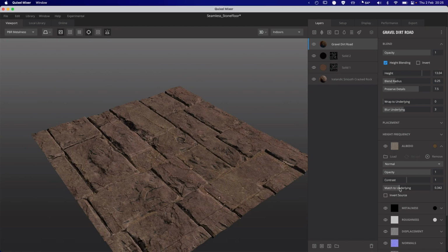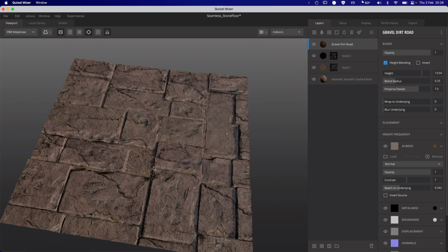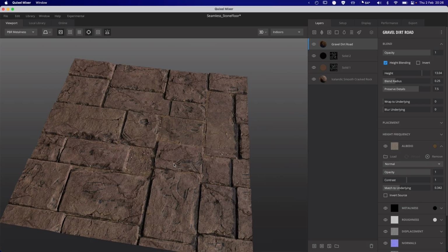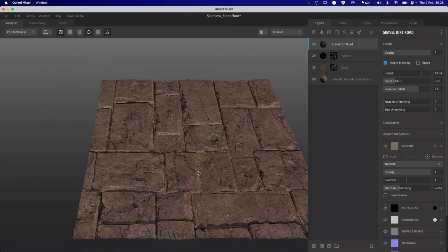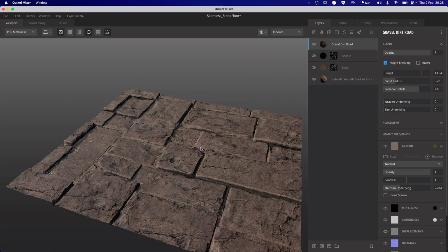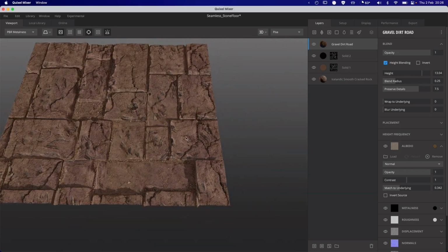It's very important that you try out different lighting modes and look at your tiles from different angles, moving your light by pressing Shift and right click and just dragging on your screen. Another way you can check to see if the contrast is too much is by switching from PBR to just albedo. And that way you're going to see only your color base without any lighting influencing it, and you can see if some of the colors are too bright or not.